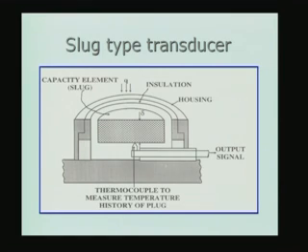This is one assumption which can be made in case delta is small and the thermal conductivity of the material is large enough, so that we can assume that. That means that the entire slug is going to actually go up in temperature uniformly throughout. And of course, in practice you will have to insulate it or isolate the slug from the rest of the universe or the rest of the space.